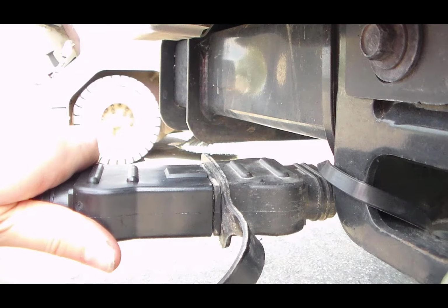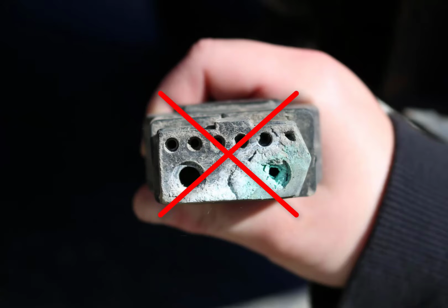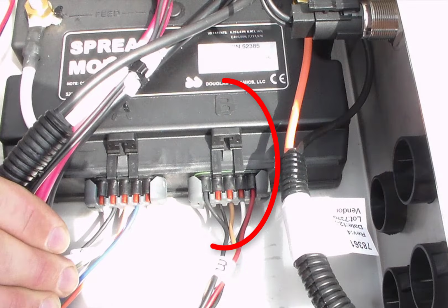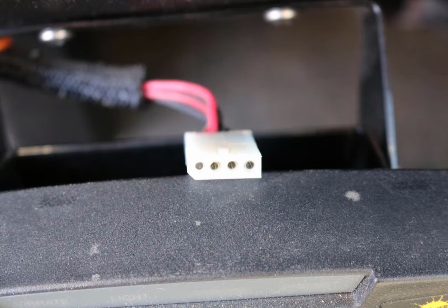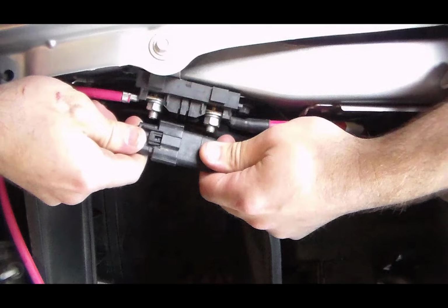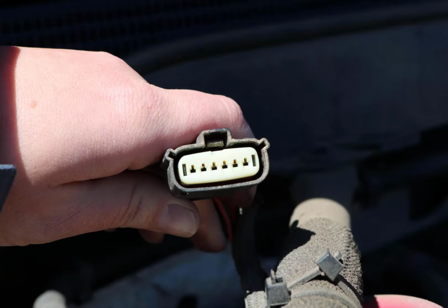First, check the connection from the vehicle harness to the spreader harness. Ensure that the connectors are tight, free of corrosion, and there are no broken pins. Check the connection of the 10-pin connector going into port B of the spreader module. Make sure there are no pins pushed out of the back of the connector causing a connection issue. Also, check the control harness connections at the back of the cab control as well as the 6-pin connector going to the vehicle cable assembly. If there are any visible signs of damage to any harness, replace that harness.